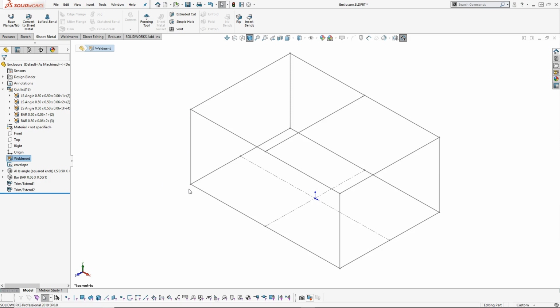Alright, so some things of note with the sheet metal: if I follow this contour all the way around, I'm going to have one piece of metal with two bends. That really isn't what I'm desiring to do, basically because of my fabrication techniques and available equipment. I don't really have the precision bending, cutting, shearing for that size of material, and I don't want to material handle the large sheets, the 36, 120s, 144s or larger. So ordering it in 3 foot by 3 foot, 36 by 36 or 24 by 48, whatever they were, is going to be manageable for this project for me.